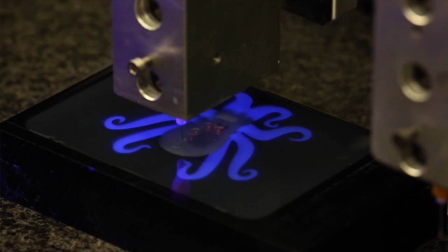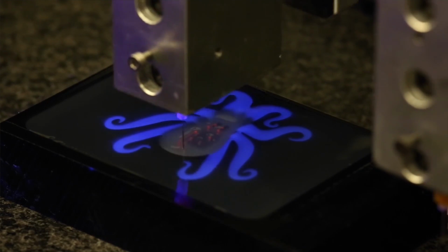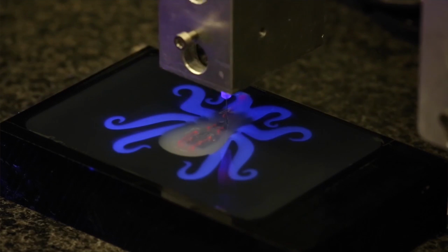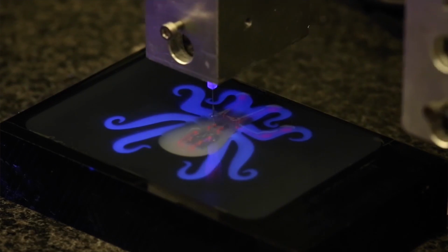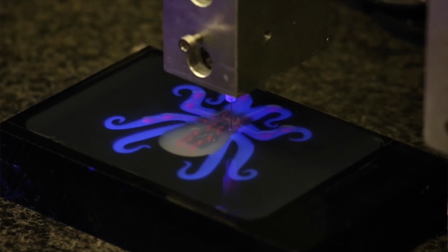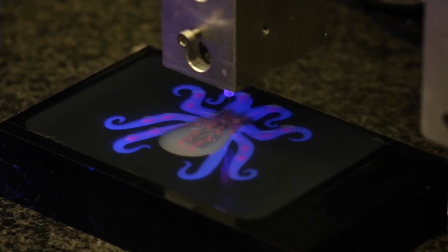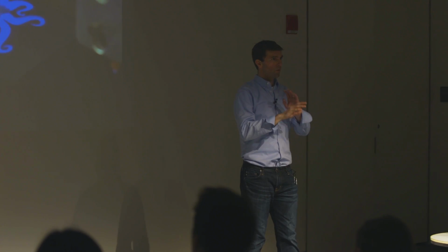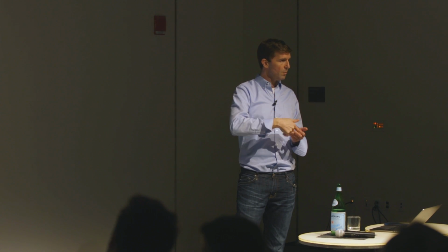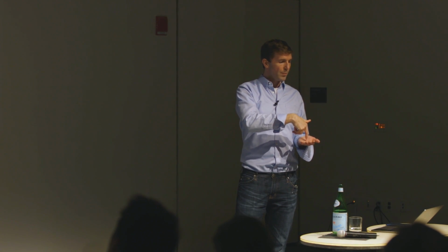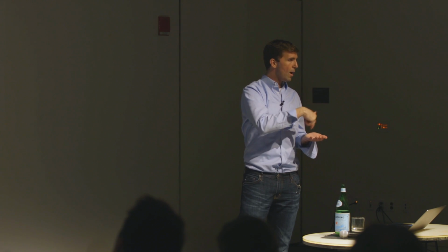This is a concept that they developed called embedded 3D printing, where what you're seeing here is a vat of uncured elastomer. This uncured elastomer is being injected with a sacrificial ink. There are all sorts of tricks associated with the rheology of this to get these to be stable structures even though uncured, but let's ignore that for a minute. They're able to inject this sacrificial ink wherever they want within the structure of this uncured elastomer. And this eventually forms the vasculature, if you will, of this robot.